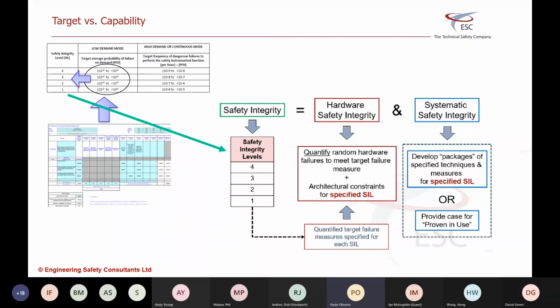If it's 61511, it's ensuring that not only you're selecting the right equipment, but that you've observed the requirements of the life cycle and the activities, management activities, functional safety assessments, verification, etc., to satisfy that SIL 1 capability, and that you can support that through the life. Okay, so that's the gateway.